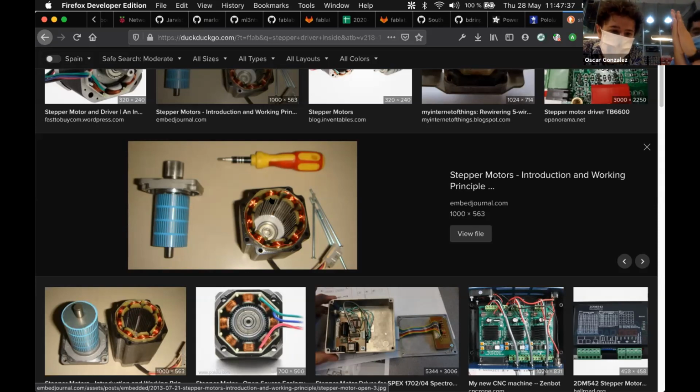So microstepping is used when you want to increase the resolution and accuracy of your machine, but you lose a little bit of capabilities. So it depends on the stepper driver that you are using. For example, this one that is purple is called the DRV8826. This one can only go up to 1/16 microstepping, but the one that we are using can go to 1/32. So depending on the driver that you use, it has more resolution or less resolution. For example, the newer generation, the one that came out this year, I think they can do microstepping of 128. That is huge.